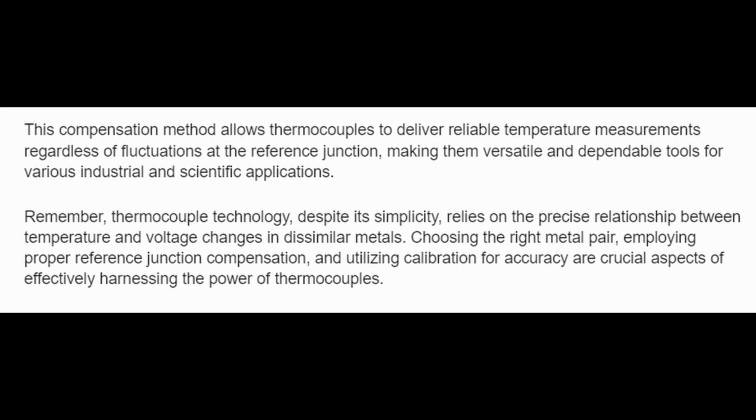Remember, thermocouple technology, despite its simplicity, relies on the precise relationship between temperature and voltage changes in dissimilar metals. Choosing the right metal pair, employing proper reference junction compensation, and utilizing a calibration for accuracy are crucial aspects of effectively harnessing the power of thermocouples.